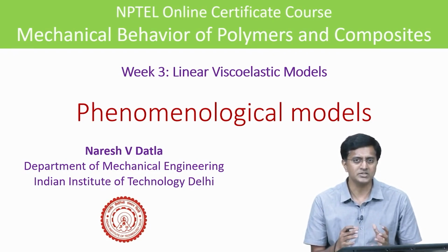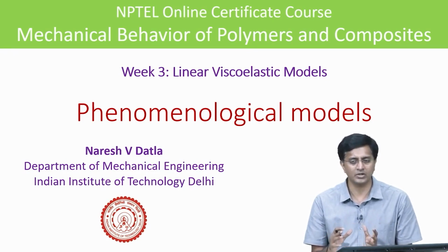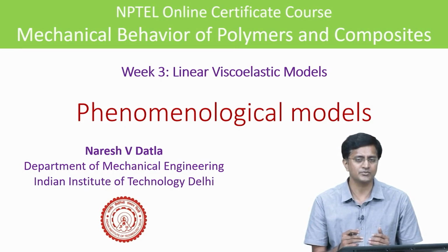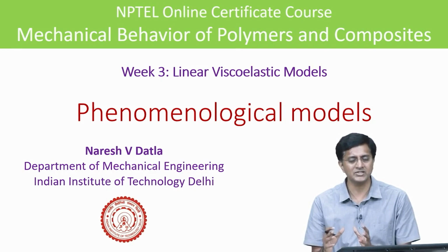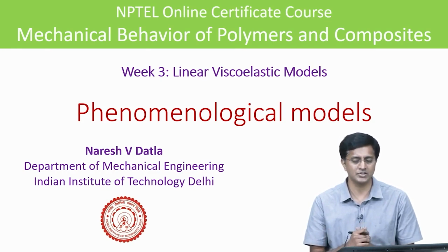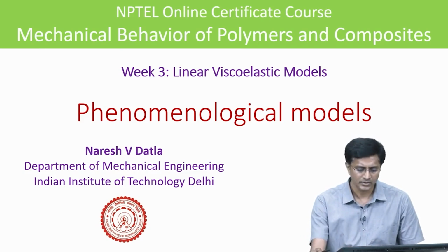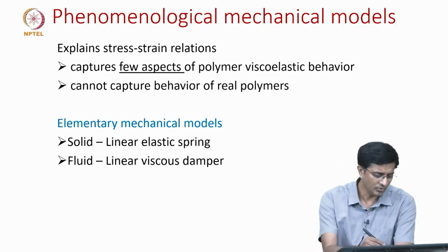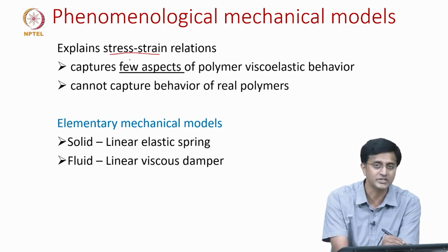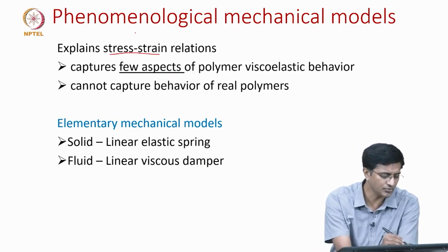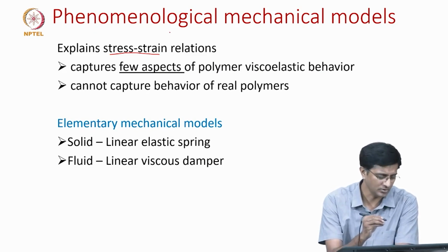What this means is that this is all good for analysis of either polymers or viscoelastic materials, but the models we will be discussing are not derived from first principles starting from observations of polymers. These only match the stress strain relationships, how a normal polymer behaves. As we mentioned, we will first start with the stress strain relations, and to describe these stress strain relations we will introduce a few phenomenological models.